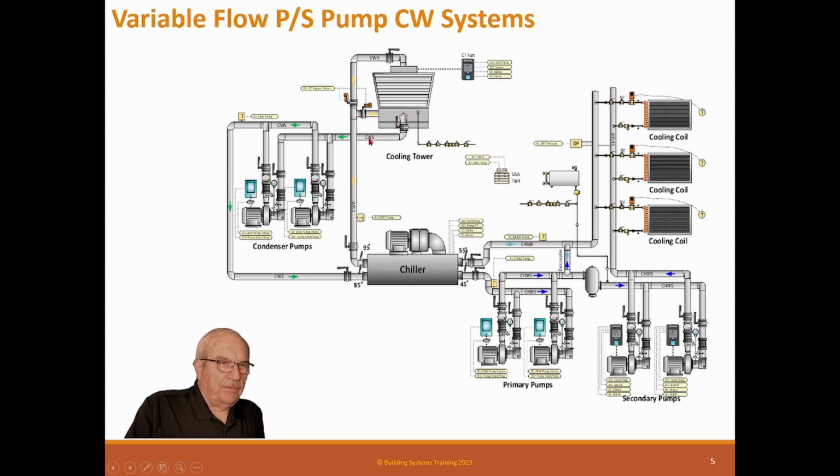If you pipe it right down here, when it's in bypass, this is now a closed piping system, and you have the pressure of the pump. What pressure is in this pipe now is in the suction of the pump. So this sees a whole different pressure profile than when it's going over the tower. When it's going over the tower, this goes back to atmospheric pressure into the basin. It's now an open system. So that piping design is absolutely incorrect.